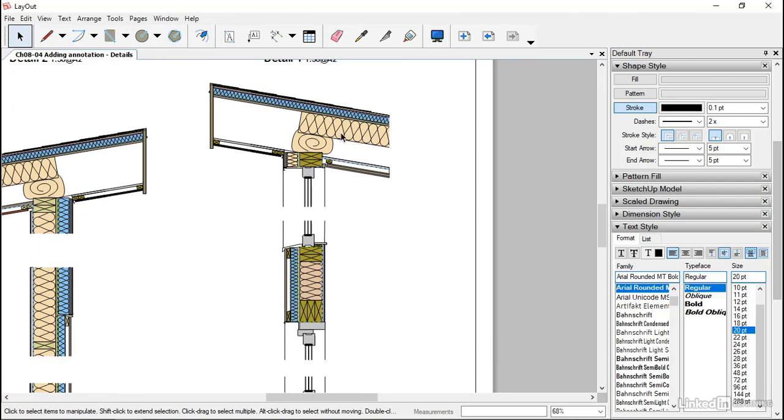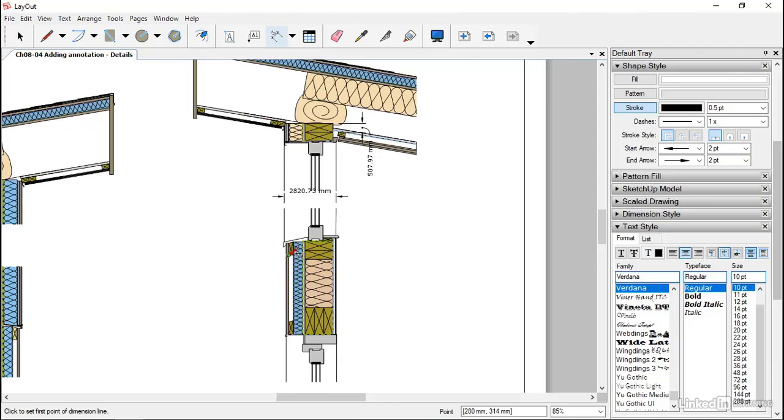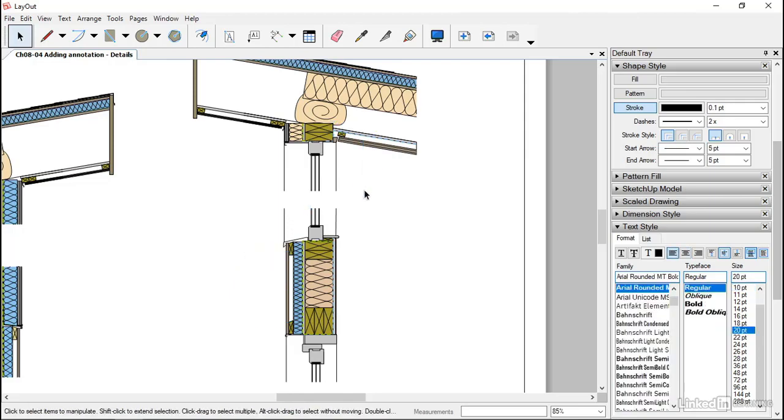So what I often see is people, first of all, putting random dimensions on things. So say the dimension tool is here, and they will start dimensioning maybe one of these things and just telling me how big that is. Now, I know it's not set to the correct scale. I'm just trying to prove a point here, even to go across the opening. Or they might think, well, this is a really important dimension between those two battens there. So before you know it, your drawing is covered with information that is completely and utterly not required. Okay, so avoid dimensions on details if you can at all help it.